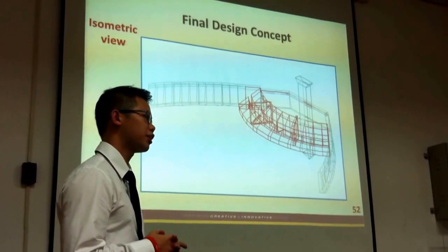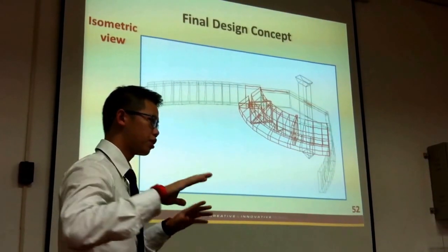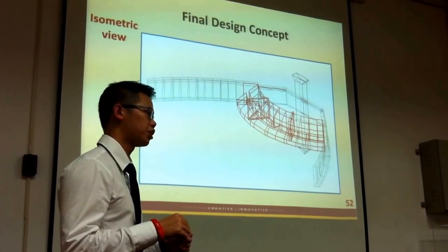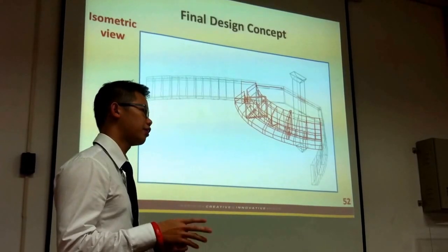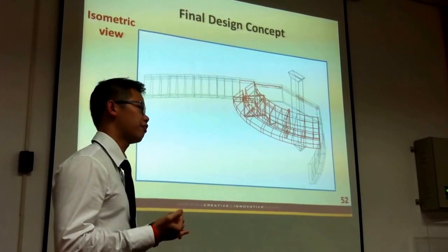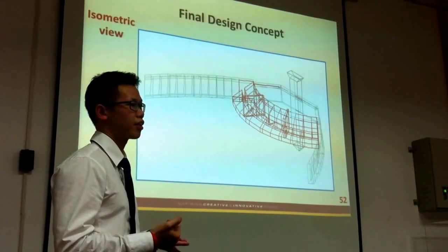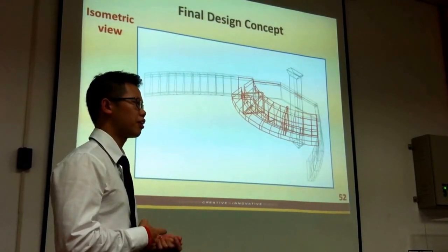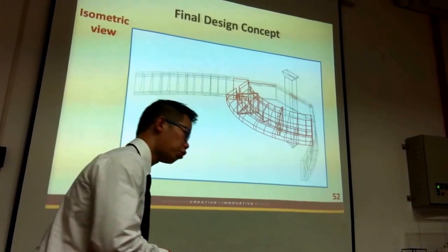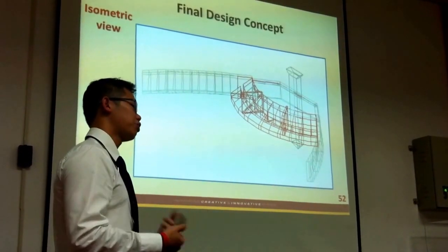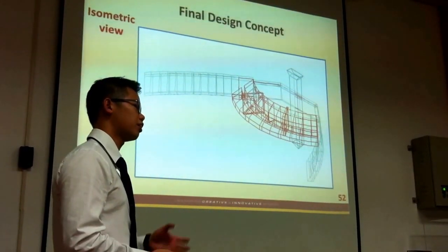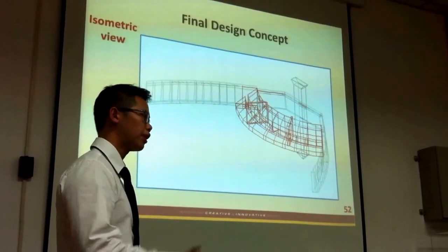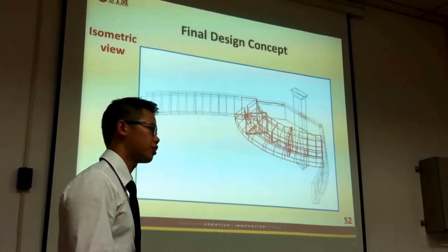From my analysis I'm actually using an average, because the wave period is from 4 to 8 seconds, I'm using 6 seconds as an average. And from there, I determine the wave input parameters, basically the wavelength, wave velocity, and wave number. So in my recommendations for future work, they can vary these wave parameters, like if they change the period and stuff. But it has to cater to the local wave conditions.